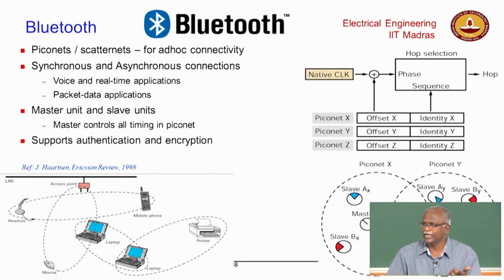Bluetooth, as you know, is a technology to connect lots of independent pairs of devices. So what you can create is a lot of parallel connections. But remember, this hopping requires you to be synchronized because you and the device that you are talking to must change frequencies at the same time. So this notion of how the clock is controlled is very crucial. If you are interested, you should read up about that. How do you maintain